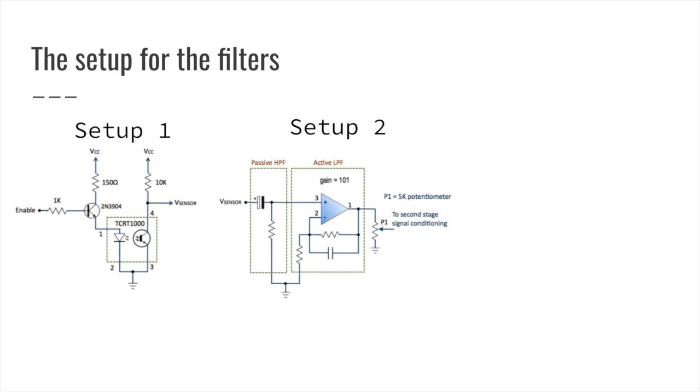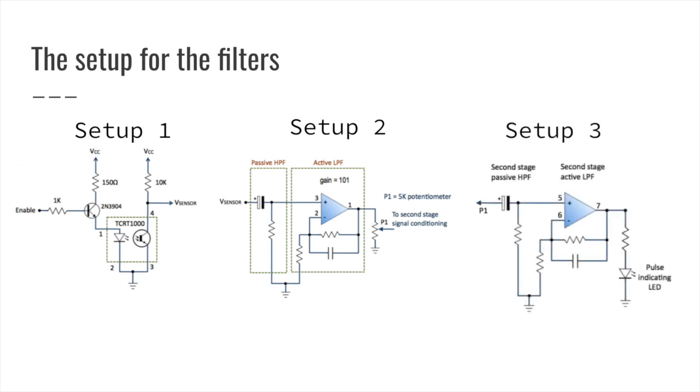The 5K potentiometer is a variable resistor that changes to fit each individual's heart rate. We added the following schematic to complete our circuit and tested the PPG with each group member. The signal was very sensitive, so it was important to keep our finger very still.